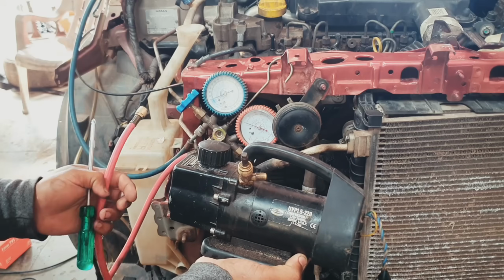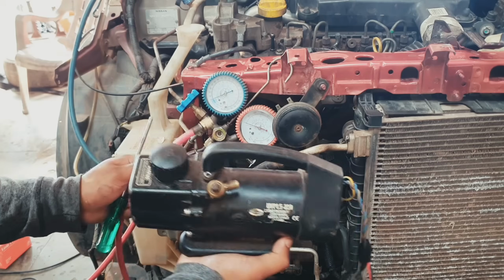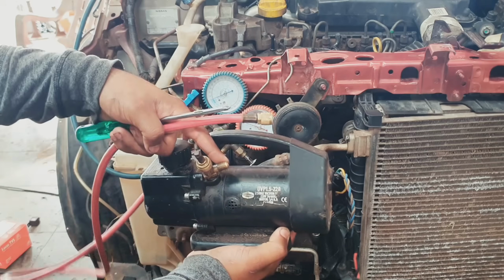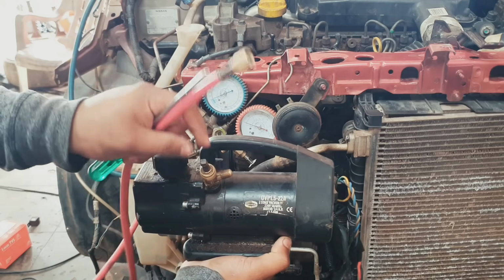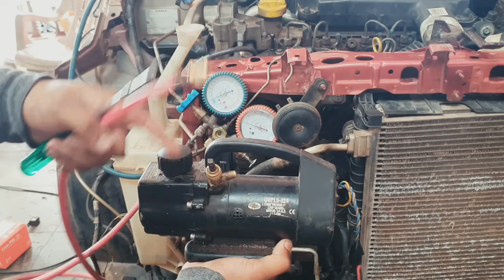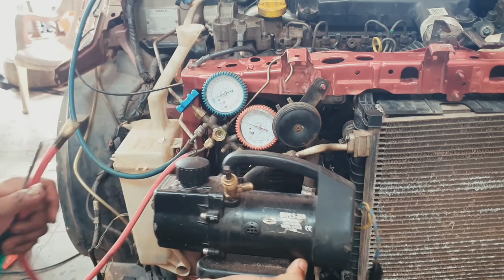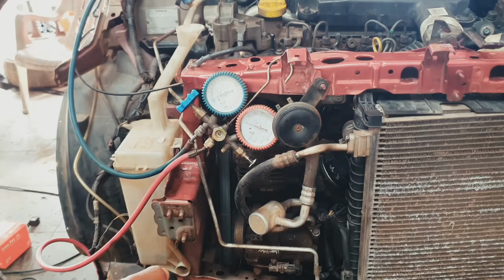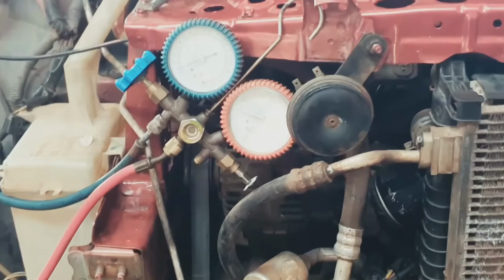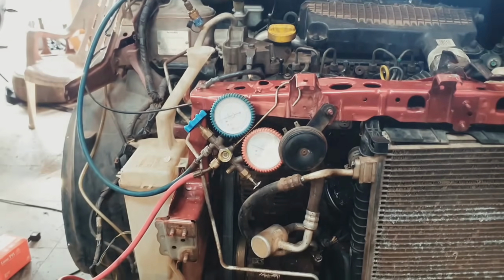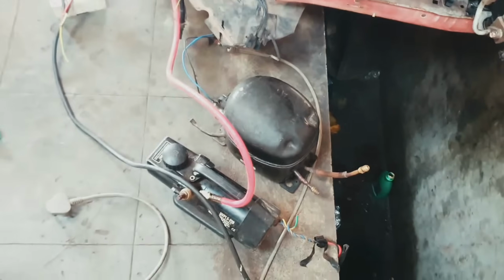You can do that in some cases, but if you want to do it like a proper professional, then this is a must. So you connect your pressure pipe here and you loosen this valve, and this will start sucking all the moisture from inside. I will explain the low side of the gauge. Actually, what I should do is take this closer to you. Now our vacuum pump is attached to this.